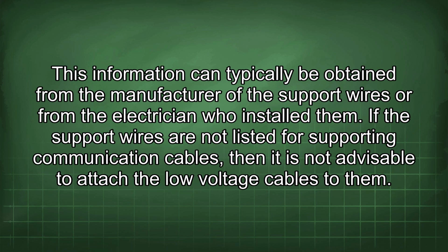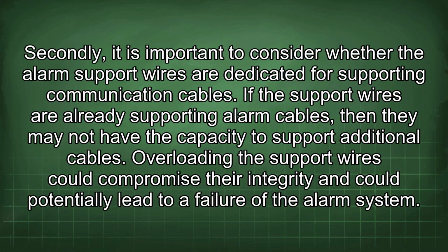This information can typically be obtained from the manufacturer of the support wires or from the electrician who installed them. If the support wires are not listed for supporting communication cables, then it is not advisable to attach the low-voltage cables to them. Secondly, it is important to consider whether the alarm support wires are dedicated for supporting communication cables.